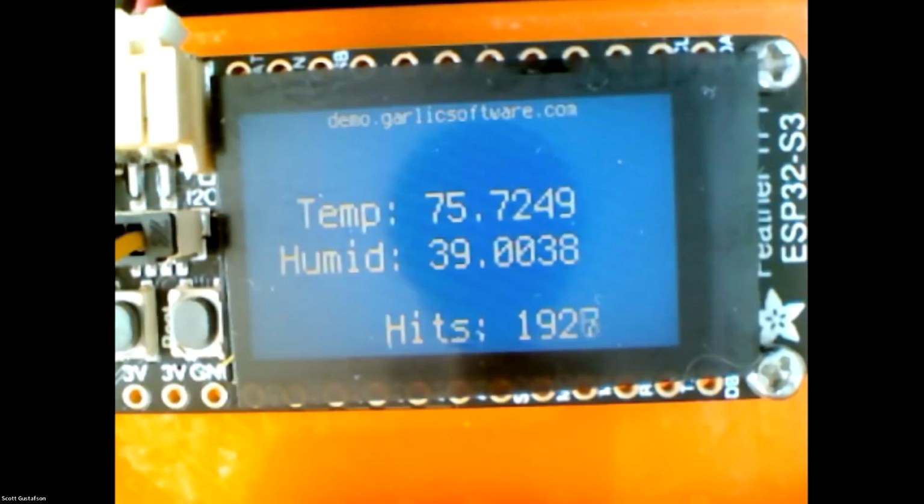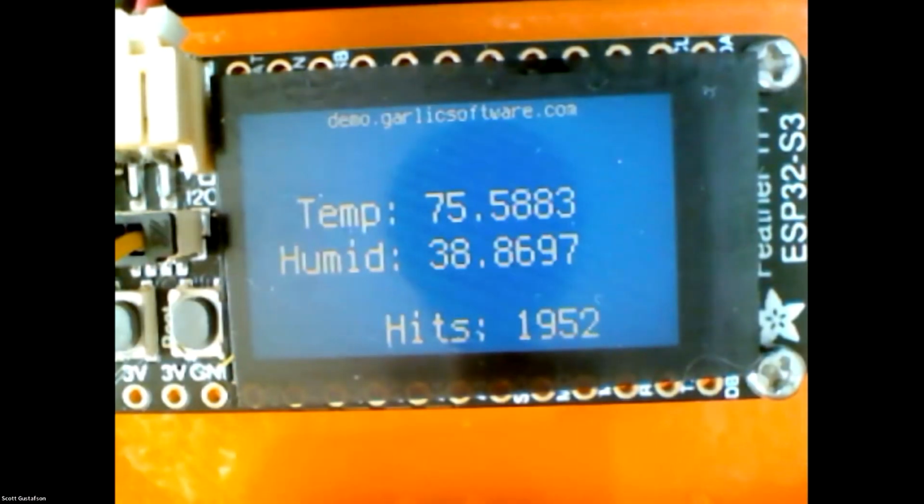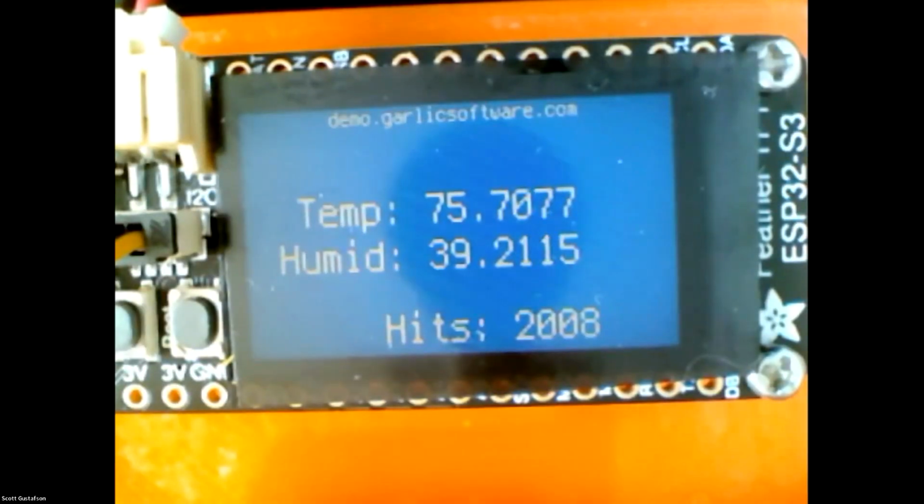You're limiting the current through that resistor, so your LED is only going to light up so bright based on the resistor. When you have 3 LEDs all running at the same time off of one resistor, the current is being divided evenly amongst those 3. So it's going to be slightly dimmer than if you had 1 resistor for each LED. I could have made it pretty and made it brighter, but I was just cheating.